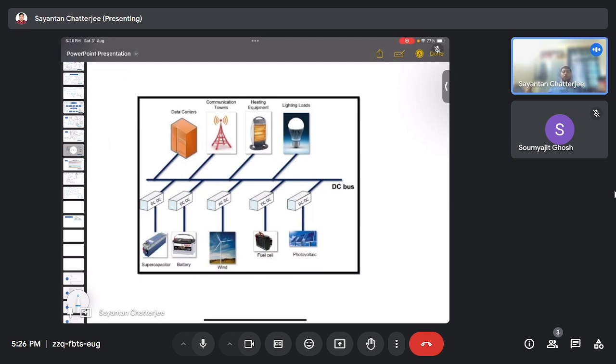Out of these huge number of loads, these loads are being operated mostly on DC, in the evening peaks, evening time, we can observe that a lot of storage systems are to be deployed, as we have discussed, but the loads are also DC. Already some loads are AC, but mostly light loads are DC. So if we can directly use that DC load, that would greatly reduce our cost because converter costs are involved, okay.